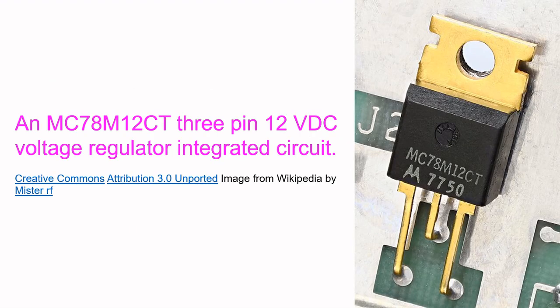Another option is to use a 3-terminal integrated circuit as an active regulator. It contains a precision reference, a high gain error amplifier, temperature compensated voltage sensing resistors and transistors, and a pass element. Some devices have thermal shutdown, over voltage protection, and current fallback.